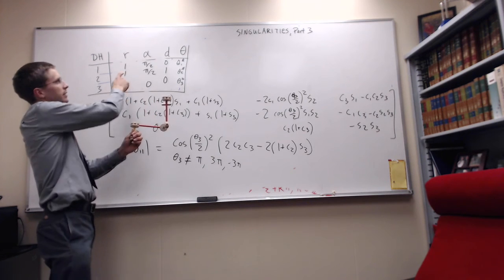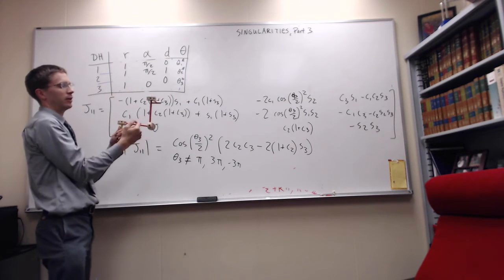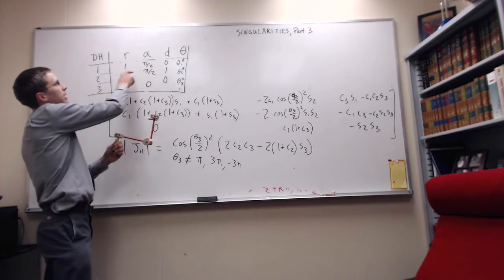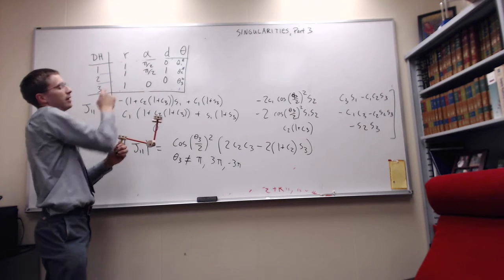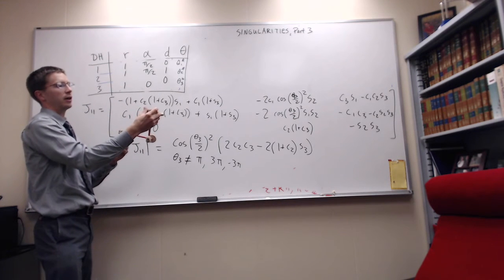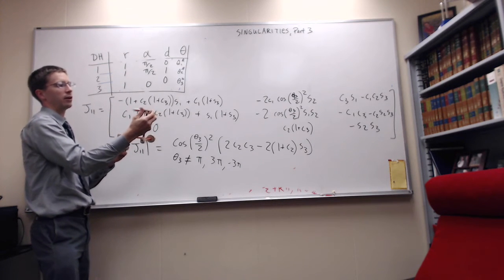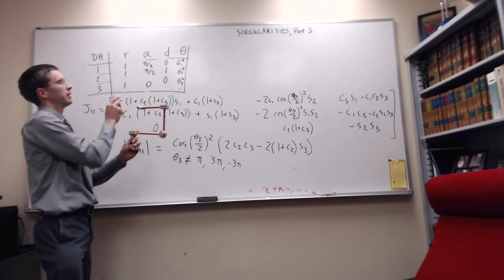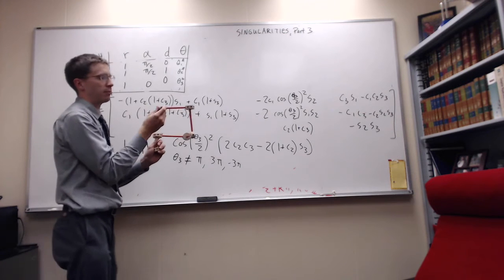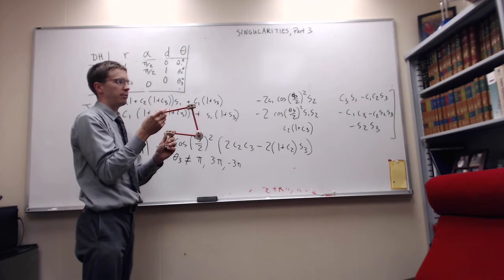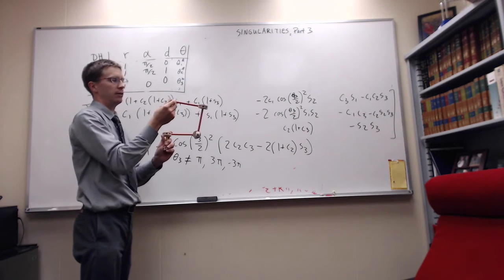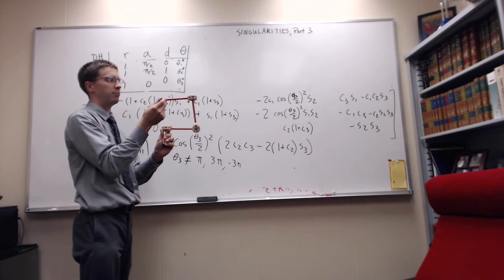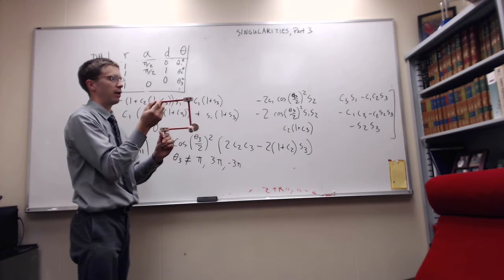But the interesting thing about this second link is its Z1 axis has an alpha twist. It's also got a D offset and a radial offset. And so our second base is right here that rotates around its new Z-axis, rotating a revolute arm that's way out here. I don't know why you'd ever make this robot, but you think about it, it's got some degrees of freedom. We can move the hand up and down, back and forth, and then rotate around.